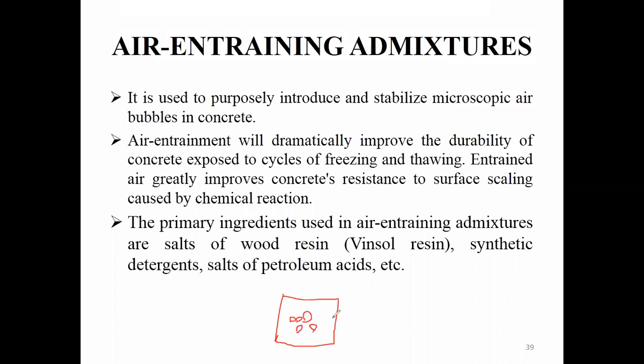It will be dispersed through the concrete. They may be interconnected; you can see here they are very close. So whenever this concrete surface is exposed to some environment, like a chemical attack, or if the concrete is placed in an underwater construction, the water or chemicals will easily penetrate through these pores, because these pores are interconnected.